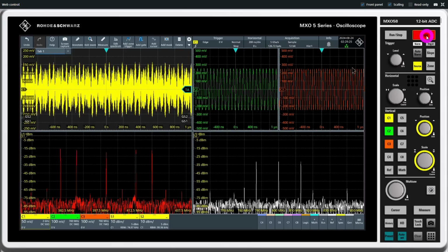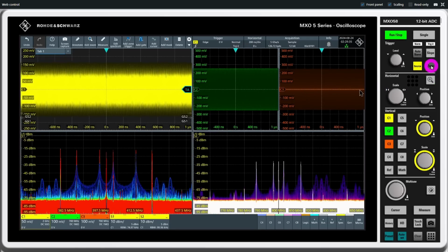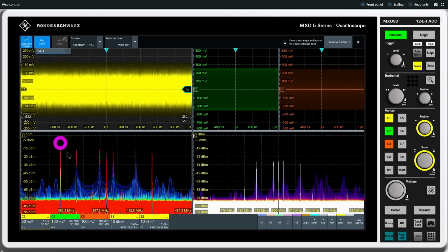So perhaps something is going on with the power of the signal at the IF port causing the value of these signals at the RF to change. Well, can we isolate that? Well, indeed we can do this. We just have to enable the zone. Now this time I want to find out when these things reach their lowest value, so we can see a transition point from when they are completely gone to when they're at their fullest value.